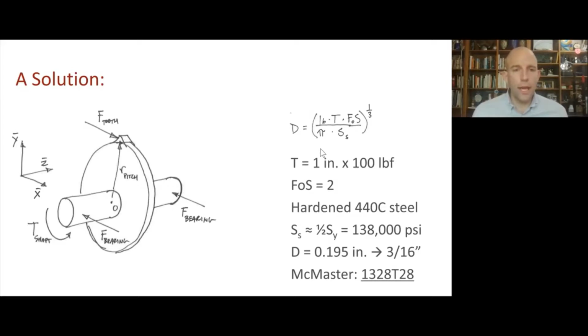All right, so working forward with the torsional stress, the diameter that's defined by the torsion loading condition, we have that the torque is 100 inch-pounds, factor of safety is 2, and once again we'll make a guess about the material. Here again, just like with the machine screws, with shafts it's a very good idea to guess at a really hard steel to start out with, because they tend to have very high strength, which results in a smaller, more compact component, and they tend to have very good strength to density ratio, which also, even though it's very dense, results in a lower mass component overall.